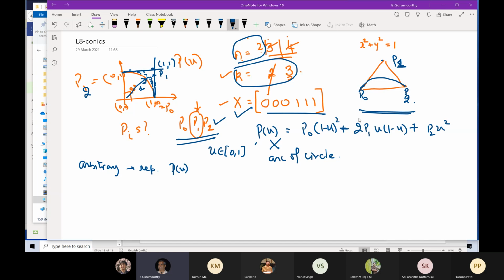I have these B-spline curves, which is a representation for any arbitrary curve that you can think of. By just moving around these control points, you can get these curves. But now I'm saying that not only must these spline curves represent arbitrary shapes, they must also represent known shapes, which are my analytical curves. The reason for this insistence is, you may recall early on that we said we want a single representation for all types of entities.